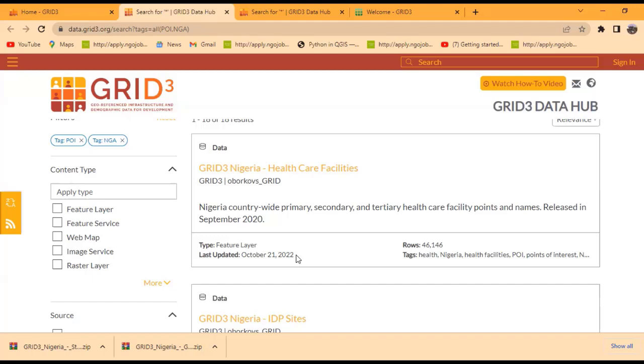When I loaded the points, I discovered that they had interchanged the names of the churches. This particular church is actually so-named, but what is showing in their data is a different name. So you actually need to verify and cross-check all the data. You don't put your 100% trust or dependence on this particular data. You actually need to cross-check, okay?